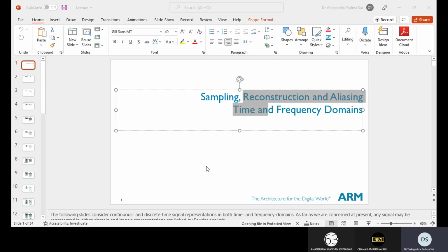Actually, here we are not explaining the sampling concept. In the next PPT I will explain it simply using a switch. You pass a continuous signal, and whenever the switch is closed, at that instant only you get your output. At all other instants, you won't get anything. What we are doing in real time is multiplying the continuous signal with some switching function.